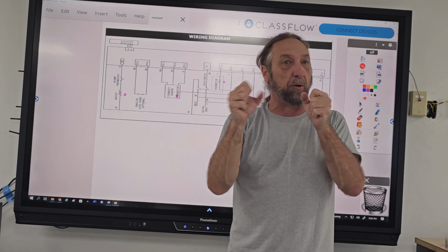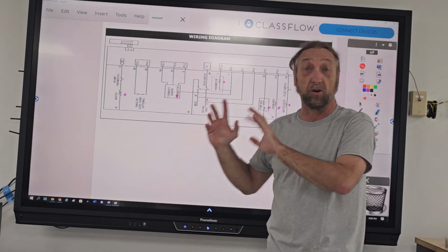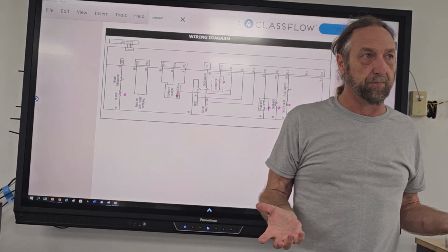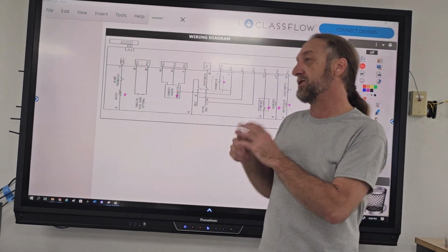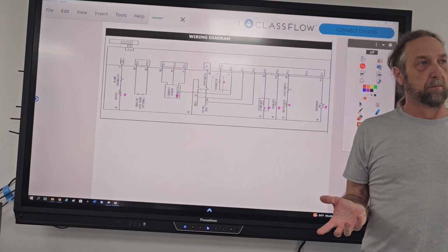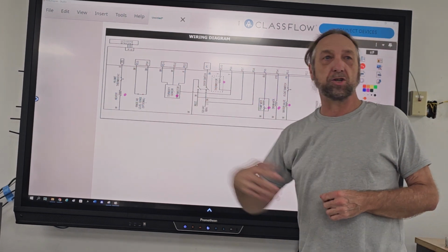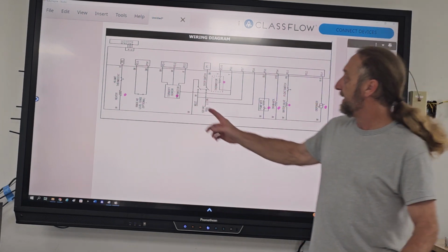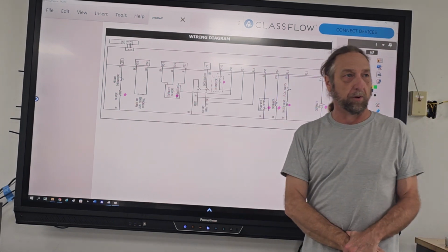If it gets too many pulses, it says, hey, this water's dirty. Throw it out, let's put in fresh water, because we're never going to get the dishes clean. So the turbidity sensor is telling the board how dirty the dishwasher is. We can add washing time, add water, drain it out, put fresh water. That turbidity sensor is communicating to the board.